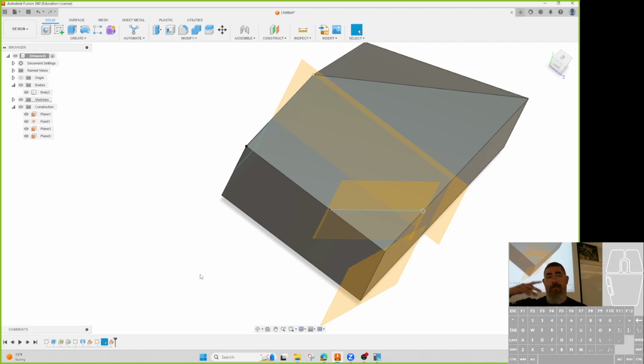So you can make these things go from sketch to entities. Instead of doing a work point here, I could have just done a sketch and put a point there. So the question is, why would we use reference geometry versus just sketched points? It's easier to change if you need to go back and change. Sometimes it's easier to change because I can just go back to the work feature. I can turn them all on and off at the same time.